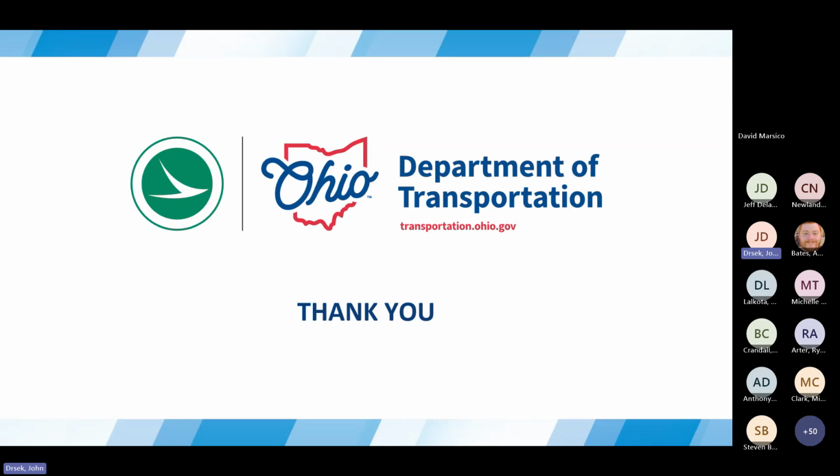Right. Other reasons for this table, a lot of it stemmed from that CFN number and not getting that for the type Bs that are under pavement. And that's been in the L&D Volume 2 for a long time. So this table has helped make it more relevant that you need those on those. It's not just the culverts. It's type Bs, I think over 12-inch in size, that's under pavement. Need that CFN number. That was another reason for the table based approach.